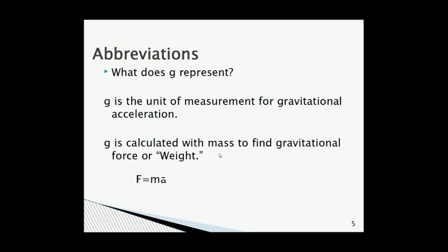Now, why is this an important formula in the vibration test field? Well, shakers are rated in force. And in order to determine whether or not the force capacity of your shaker is capable of performing a test, you will need to multiply the sum of your masses times the acceleration of your test profile.